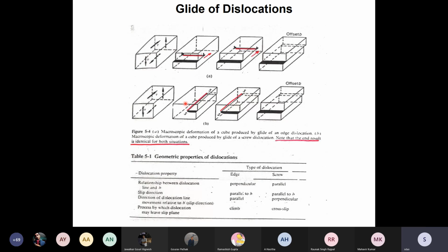Even though they are not loaded in the plastic regime but in the elastic regime, time dependent deformation takes place in them. That is called creep. So before creep becomes significant, the blades are replaced. They are very expensive, but life is a lot more expensive than those jet engines. You cannot put a price tag on life. What happens? Why do they creep?